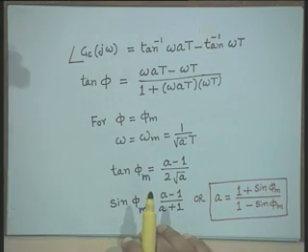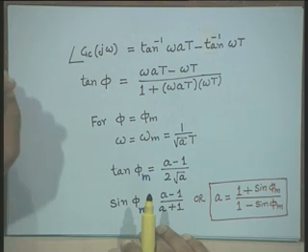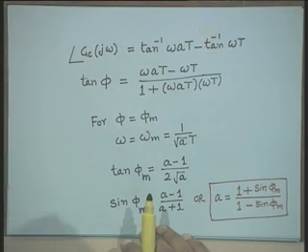Now, the question arises: what is the frequency at which I should design my power system stabilizer? This frequency is the rotor oscillation frequency. However, we have seen that this rotor oscillation frequency varies over a wide range, and therefore the power system stabilizer should be designed for one frequency, but when the frequency increases or decreases from that value, it should still be in a position to give reasonable phase compensation.